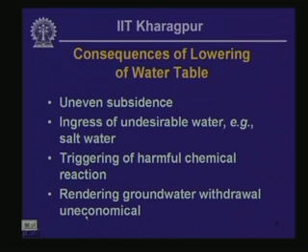So, particularly in coastal areas such as the coastal areas of Tamil Nadu, coastal areas of Gujarat, and many other places internationally in fact as well, because of excessive lowering of water table, salt water has entered the originally non-brackish or sweet water aquifers, and they have in fact displaced the sweet water aquifer further inland, and that has led to great difficulty in water use associated with the use of the irrigation water wells within the affected area.